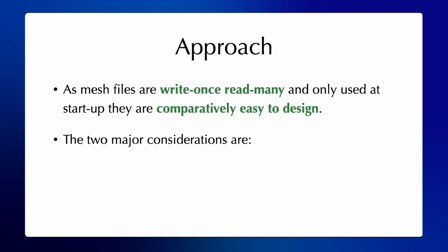Now, meshes are fundamentally a write once, read many kind of arrangement, in the sense that you create a mesh and then you may run dozens or even hundreds of simulations on that mesh as you get your simulation up and running, and then you restart it periodically every 24 hours based off of your job allocations. So what we should have here is, because they are write once, read many, they're actually quite easy to design.